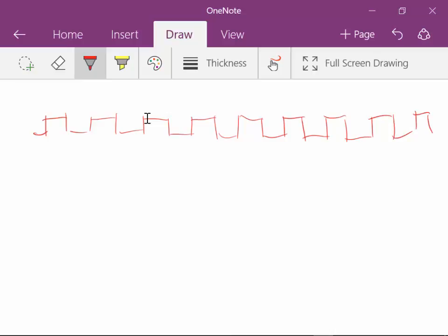And we won't carry it all the way through, but we're going to toggle at these points in time right here, on the trailing clock edges, right there. That's where we toggled it. Last time we toggled on the leading clock edges. Now, let's look at Q0. Q0 is going to toggle, starts out at 0, and it's going to go high here. It's going to go low here, high here, low here, high here, low here, high here, low here, and back to high there.